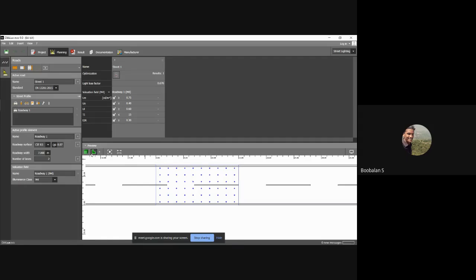Now here, see, we'll have two options. This is called a 2D diagram. It is showing only the x and y axes, right? Here, see the blue color dot, this blue rectangular shape. Only in this area am I going to calculate my luminaire systems, right? So how much light is needed, watch carefully. Here you can see 0, 5 meter, 10 meter, 15 meter. Within the 15 meter I'm going to calculate my lighting systems. You are able to increase your lighting system beyond that, up to 50 meters also, right?